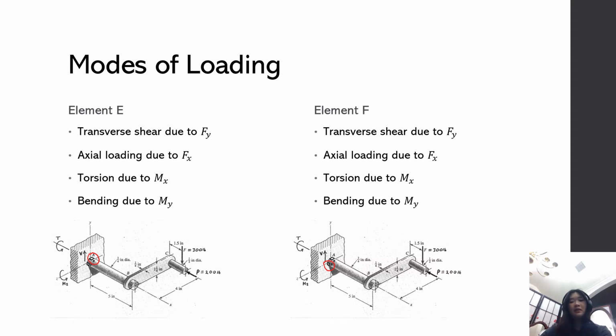Next, looking at the forces acting at element F, there's a transverse shear force due to F of y, there's an axial loading due to F of x, and there's a torsional force due to the moment about the x-axis. There's also a bending due to the moment about the y-axis.